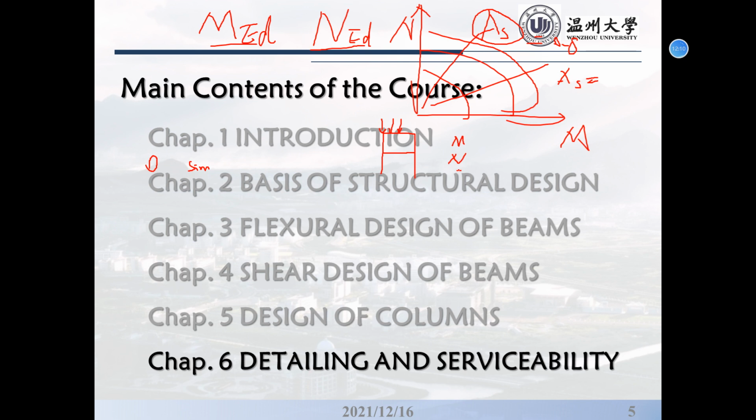And for columns, if they do not suffer wind load, only gravity or live load, so there is no horizontal load. So the shear force we do not consider here. So only the moment and the axial force we can get. For the axial force, NEd may be easy to get, right? Because it's along the columns.